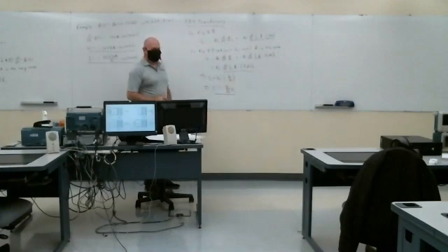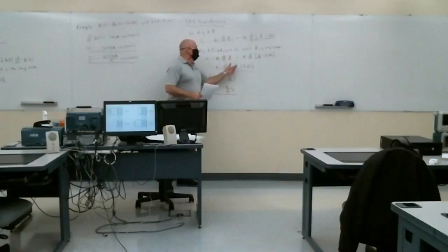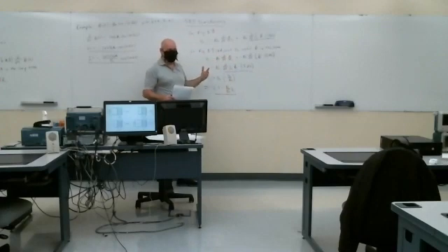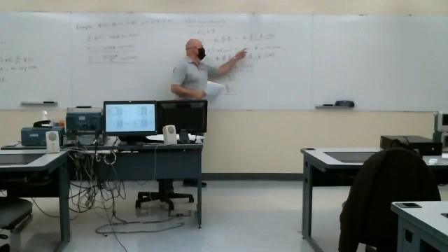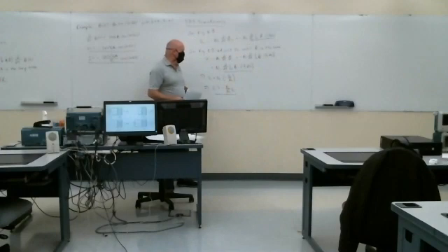I get a direct relationship between the voltages. It depends on nothing more than the turns ratio. I am also relying on the fact that the core has the same cross-sectional area for both coils, so the surface integral is the same in both of these cases.